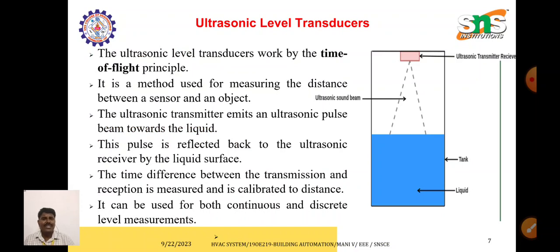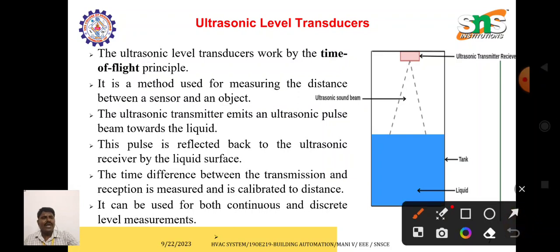And the next one, the ultrasonic level transducer. Here there is an ultrasonic transmitter device which is placed at the top of the tank. We send the ultrasonic signal, it touches the water, and the same signal is reflected back to the same ultrasonic transmitter. It works on the time of flight principle.